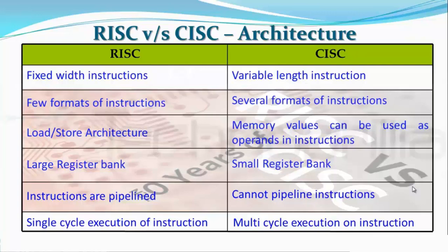In RISC, instructions operate directly on registers rather than memory locations, as opposed to CISC. RISC architecture is also known as load-store architecture, as the implementation is like: load from memory into register, do operation on register, store register back into memory. In other words, only load and store operations access memory, and all other operations are register to register.